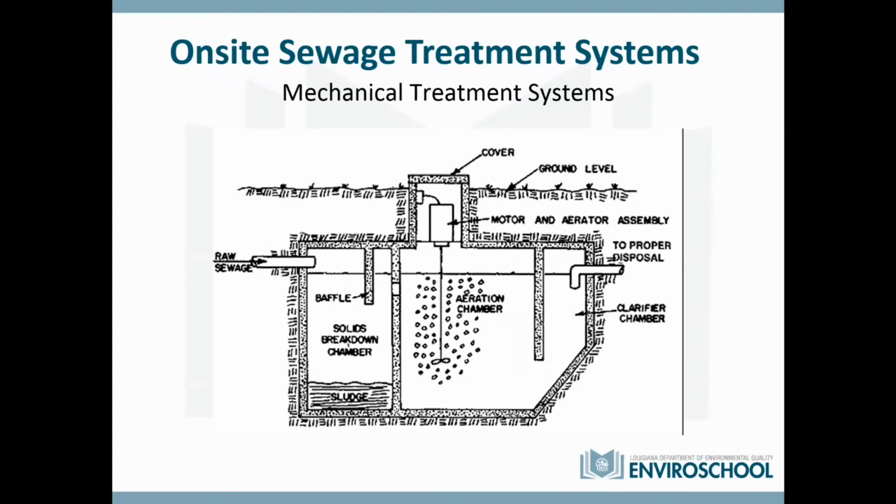This schematic looks like it might be one that has a little propeller at the bottom. And mostly what I see, just from my experience, are ones that have air blowing into it. But it's basically the same thing. You're providing some kind of means of producing or adding oxygen into that water. And what that does, again, is get the aerobic bacteria excited and hungry, and they break down the solids.